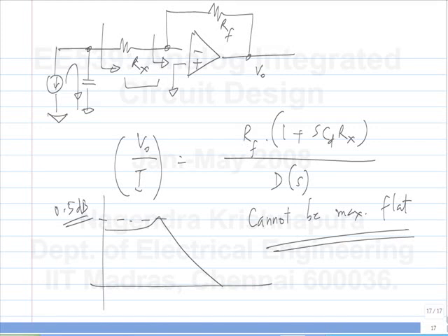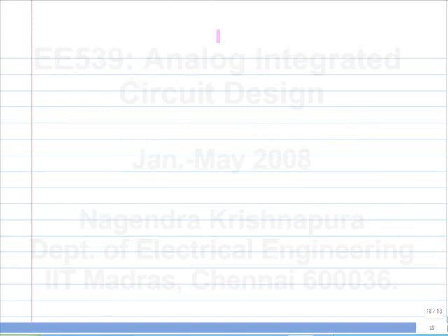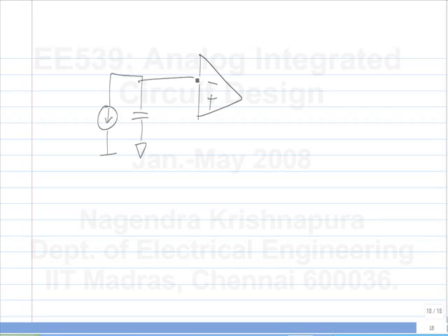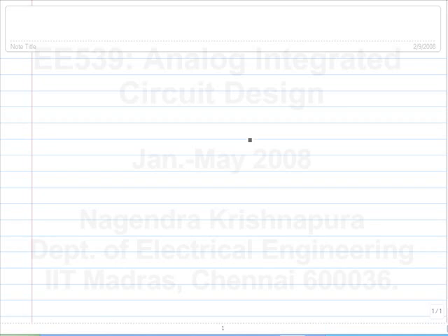Have you built inverting amplifiers or photodiode amplifiers, any of you, on a PCB? Nobody? Okay, so let's then proceed theoretically. First of all, the circuit I gave was this, right? What he is suggesting is that the reverse bias on the diode changes because of the resistor. Let's look at it and decide whether it's a problem.